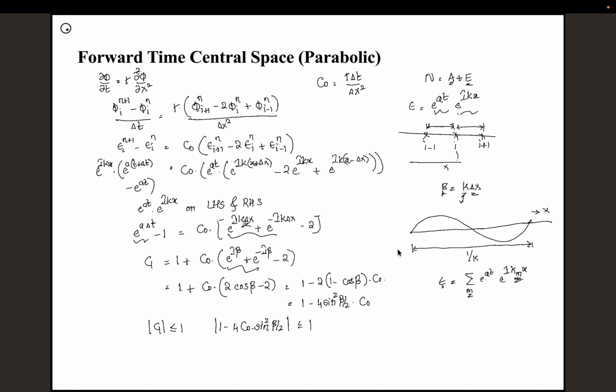and for this we will be finding the values of the Courant number, and this Courant number is the one that we will be interested in. So we know the gamma for this particular problem. Gamma is the diffusion coefficient, and delta x is the spatial grid I will be using, depending on the problem we are solving. Let's say if it is a boundary value problem, then we know it is a parabolic equation. Of course it is a nonlinear PDE, but we know the delta x from the model requirements. We know the delta x has to be very small, close to the wall, etc. So what is the value of time step that I need to use?